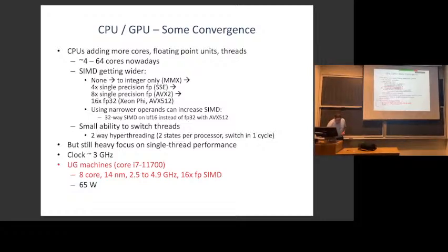It's still a net win, but you're dissipating so much power. The processor is monitoring its power consumption, its heat dissipation. It'll throttle its clock back. It will also drop its voltage, because to run at 2.5 gigahertz, it doesn't need as high a voltage, which also helps its power consumption.